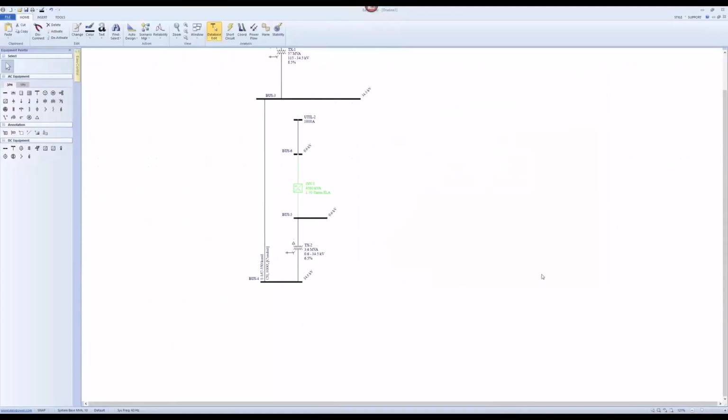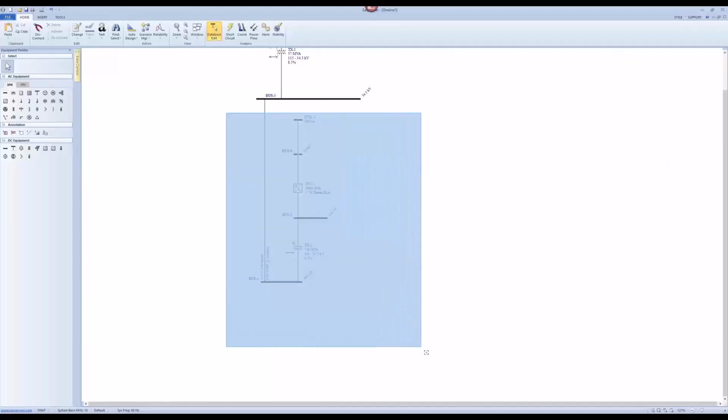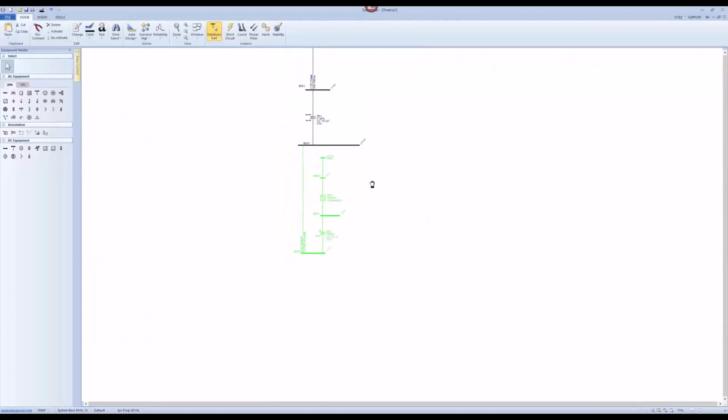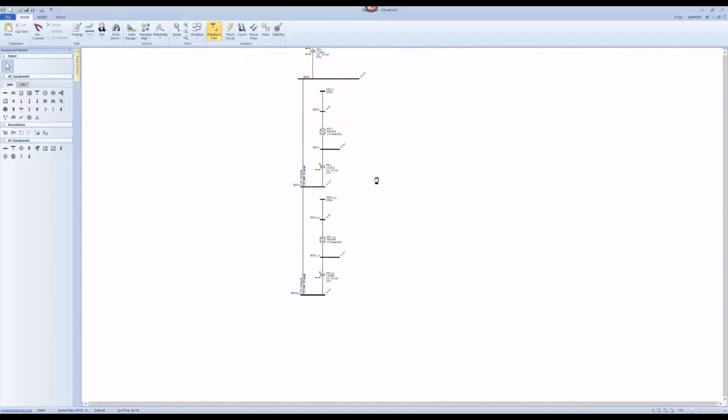That's all. I'm done with my harmonic modeling because all those harmonic spectra information comes from my manufacturer, right? And I have converted from ampere to percentage, which is what EasyPower takes as input, right? So this is a full set of the harmonics model of my inverter and my one section of the collector cable system. So I keep adding things on.